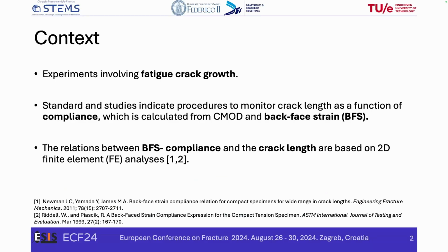In the context of experiments involving fatigue crack growth, it might be of interest to correlate the compliance measurement in the specimen with respect to the crack length. For this reason, different standards have established relations to do so based on backface strain compliance, based on 2D finite element analysis, assuming straight crack fronts.